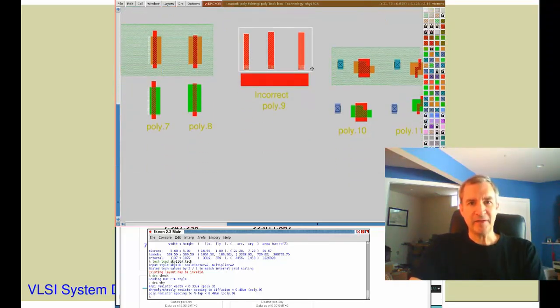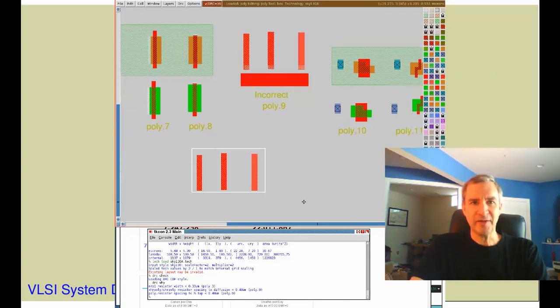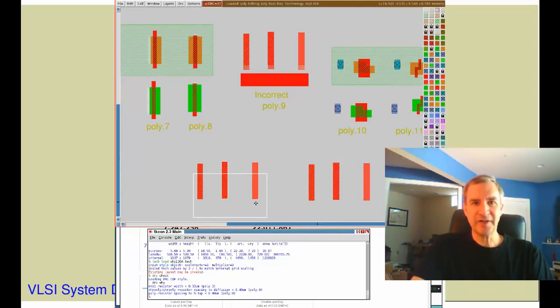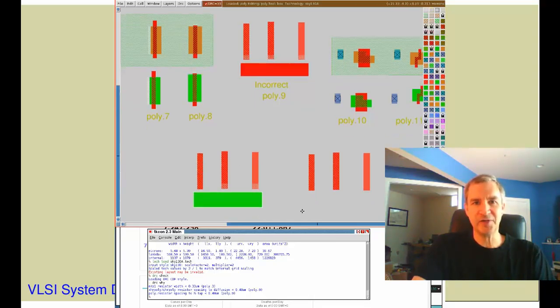We'll need to copy the 3 resistors. Because there are a number of different varieties of diffusion and tap, we'll make several copies and check against N diffusion, P diffusion, N tap, and P tap. In Magic, those layers are called NDiff, PDiff, N substrate N diffusion, or NSD for short, and P substrate P diffusion, or PSD for short. N-type diffusions are always drawn in green, and P-type diffusions are always drawn in a tan color.